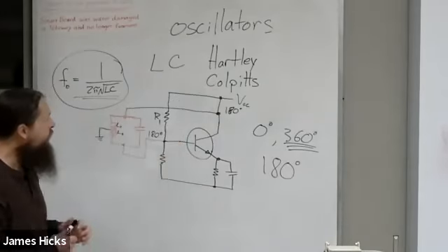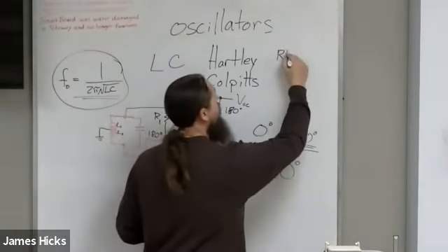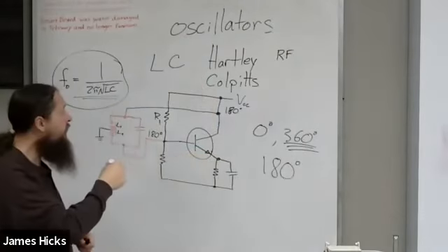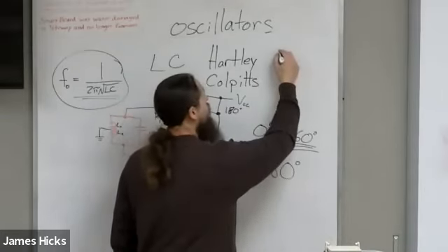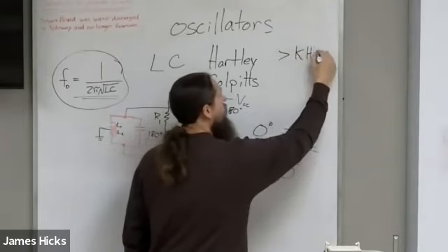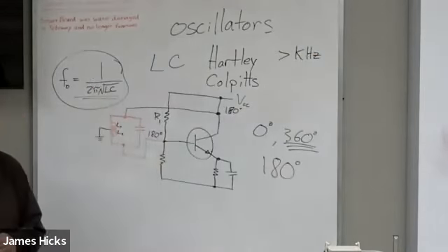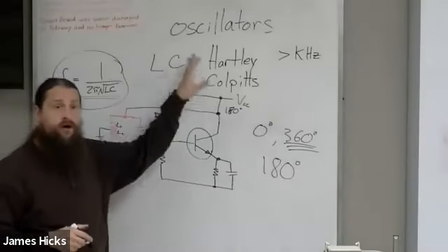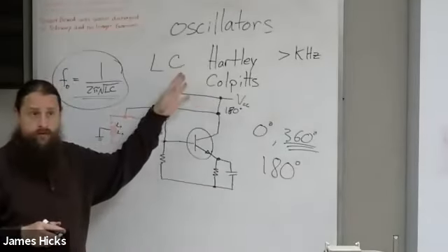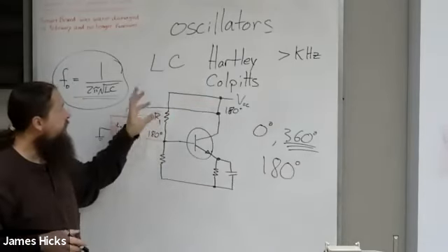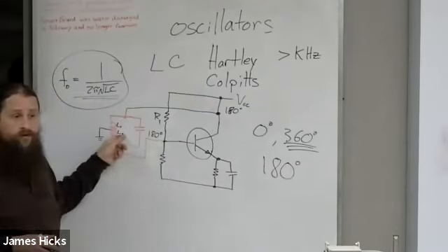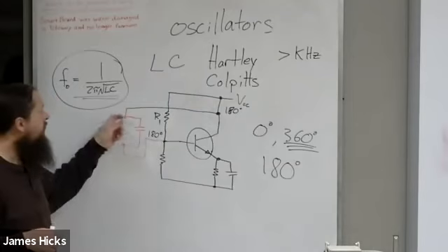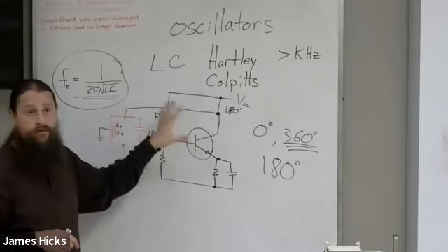The Hartley oscillator is good for radio frequencies and higher, greater than kilohertz frequencies. It's not good for really low frequencies, like audio frequencies, and the reason is that to get to low frequencies, your inductor is physically quite large. So these Hartley oscillators are both high frequency.